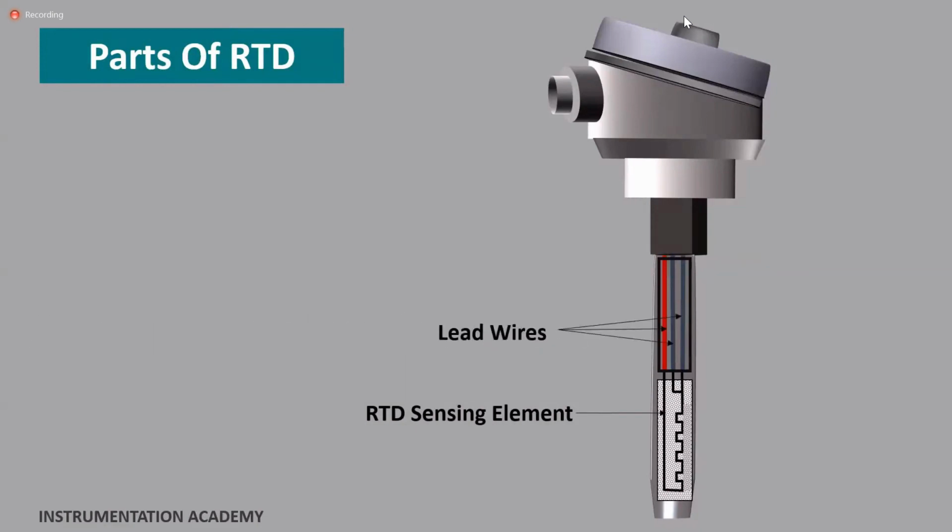Lead wires. Lead wires are attached to the sensing element and then pass through the sensor sheath. Lead wires connect the sensing element either directly to the DCS or to a temperature transmitter connected to a DCS. Sensor sheath. The sensor sheath is constructed of metal and holds most of the component parts of the temperature sensor. The sensor packing, typically magnesium oxide, surrounds the sensing element and is contained within the sensor sheath. The sensor packing decreases the impact of process vibration on the sensing element and thus ensures a more accurate measurement.